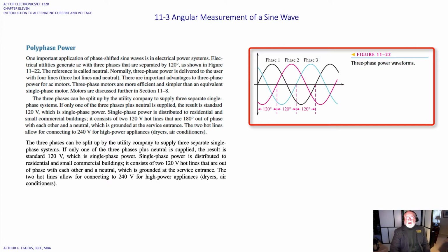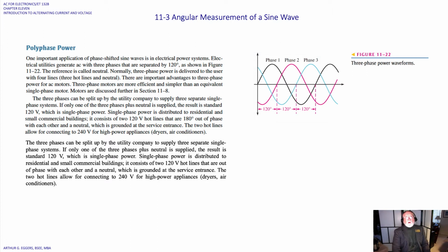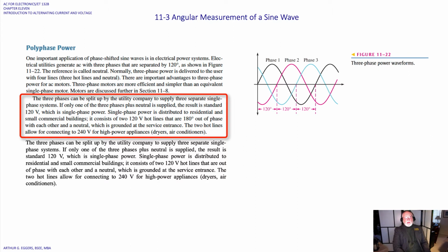And typically, in a system where you have three-phase power, like your residential neighborhood, you normally don't get all three phases. The phases are separated out and managed and distributed into a neighborhood so that the power is distributed properly between the residential houses.